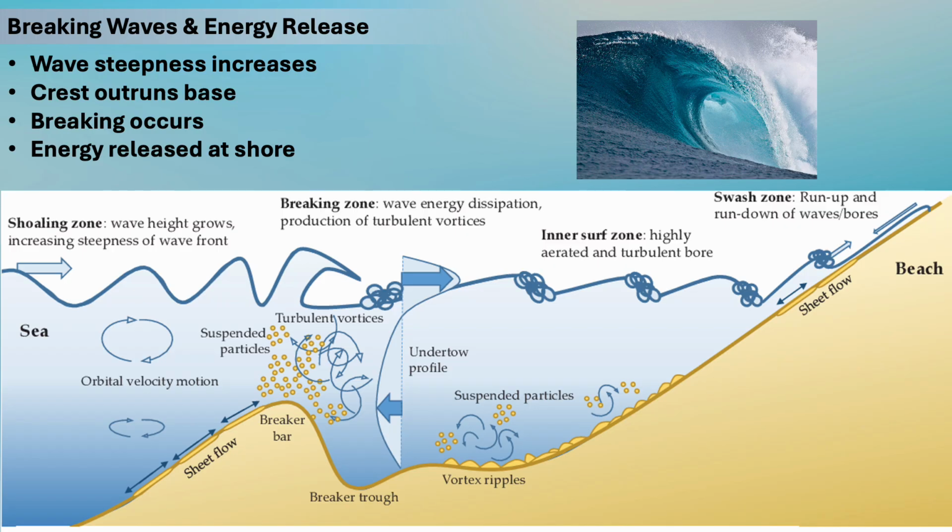Breaking converts organized wave motion into turbulence. This turbulence transfers energy to the shoreline and to sediment particles. Breaking waves are therefore the primary mechanism delivering energy to the coast. I include this slide in today's lecture as a reminder that erosion and sediment transport are not caused by water motion offshore, but instead by breaking waves in shallow water.